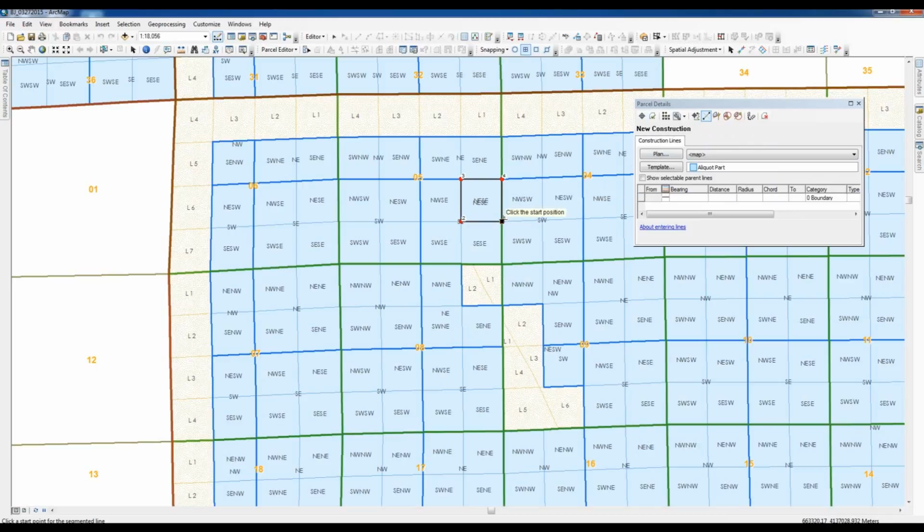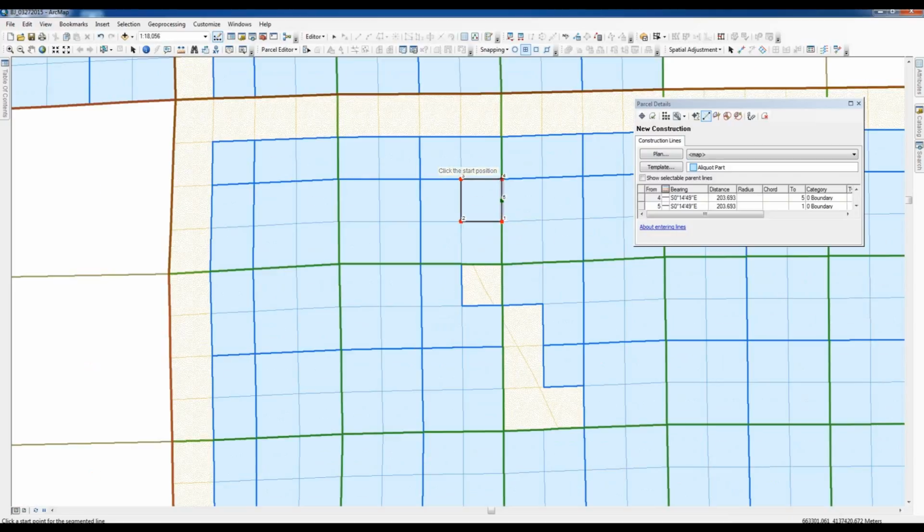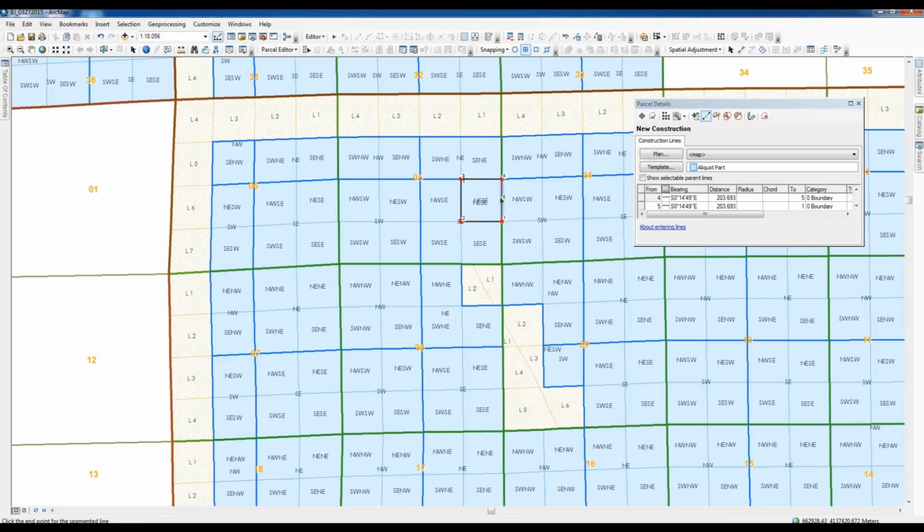And we're going to start down here at this corner, select a beginning point, you right click, opens this window. We want a midpoint, so we want it in 2 equal segments. Click the endpoint. Okay, now we need to go all the way around the polygon for where we need these new parcel points. So we only need 1 segment here, no division really. Endpoint.